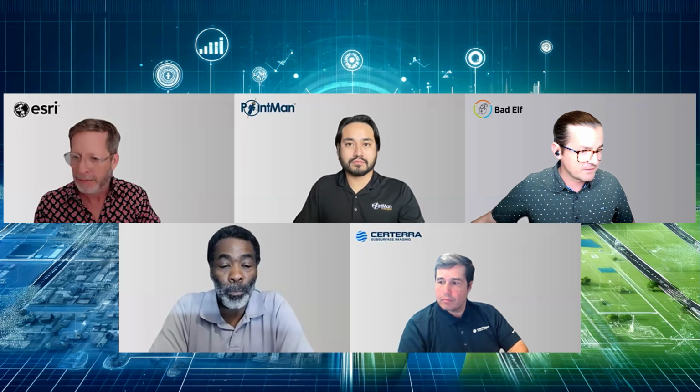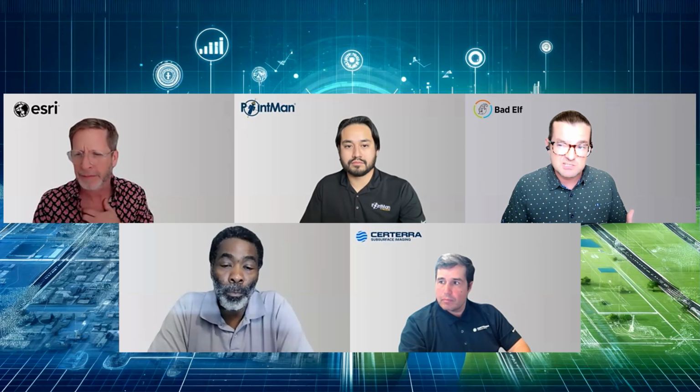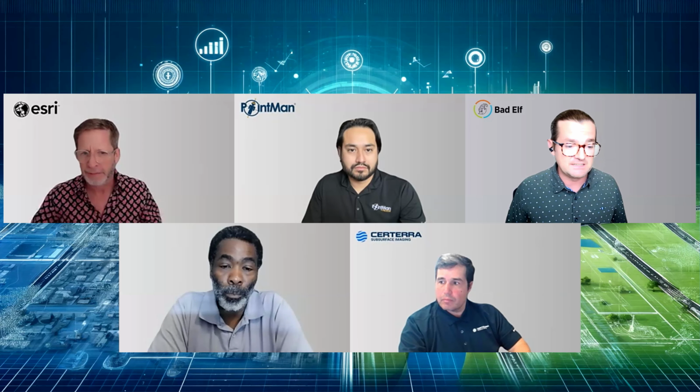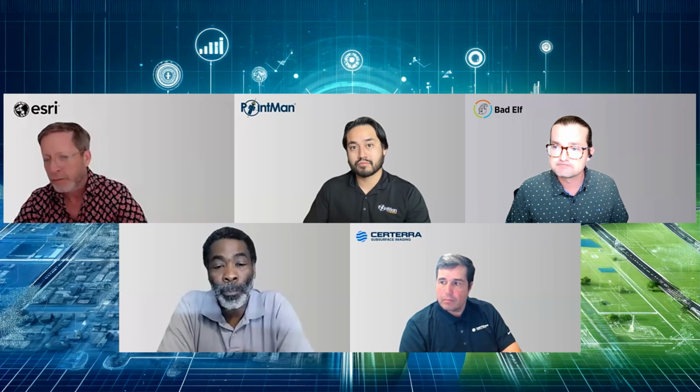But yeah, we are a GPS. And I'll say one more quick thing. Your cell phone has a GPS built into it, an integrated GPS, but it is not going to get you much better than about 15 feet of accuracy, or what we call precision. The moment you need to get to mapping grade at a meter or better, or survey grade, and there are lots of ways to define that, but let's say 0.2 of a foot vertically, Bad Elf is a way to do that. So yeah, we are a low-cost GPS.